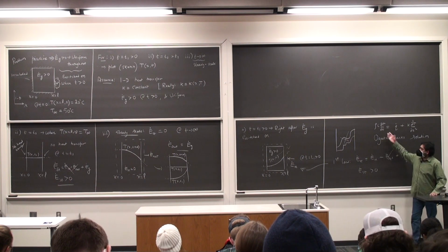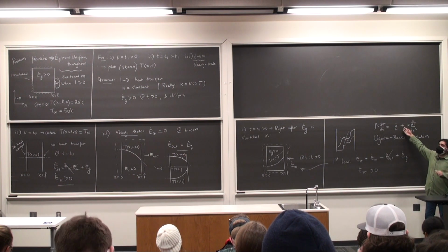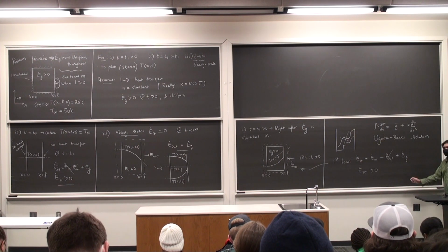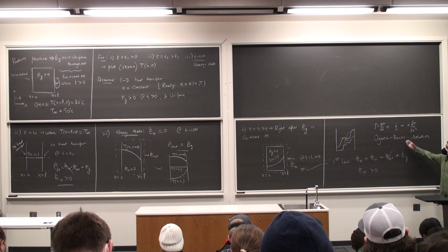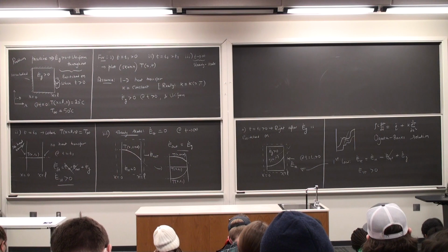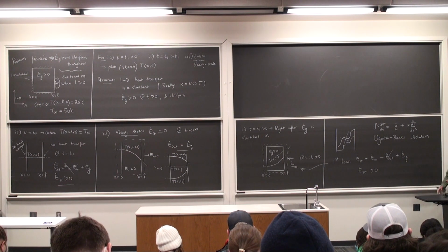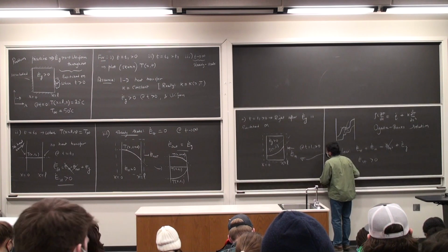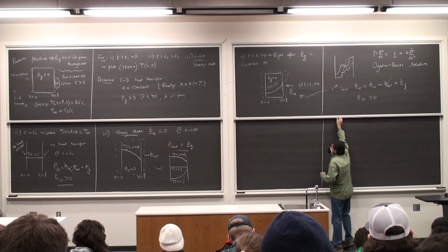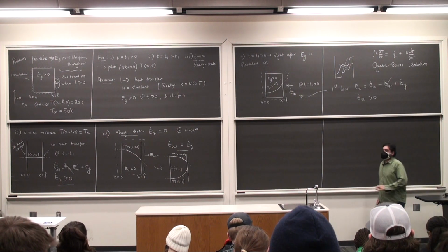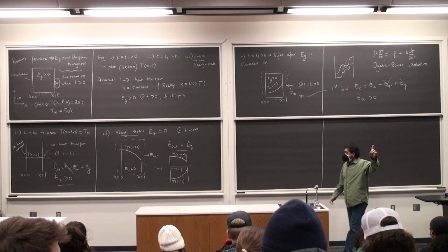And of course, one can solve this. This is not very difficult to solve. One dimension is not very difficult to solve. 2D, you need to do numerical techniques. Closed form solutions are very rare. And for different characteristics of heat generation, the problem becomes more and more challenging. For different functional dependencies of the thermal conductivity, it becomes much more messy. So numerical solutions are the way to go. Alright, so this was a small digression from where we were in the last lecture, where I started my radial system heat transfer.